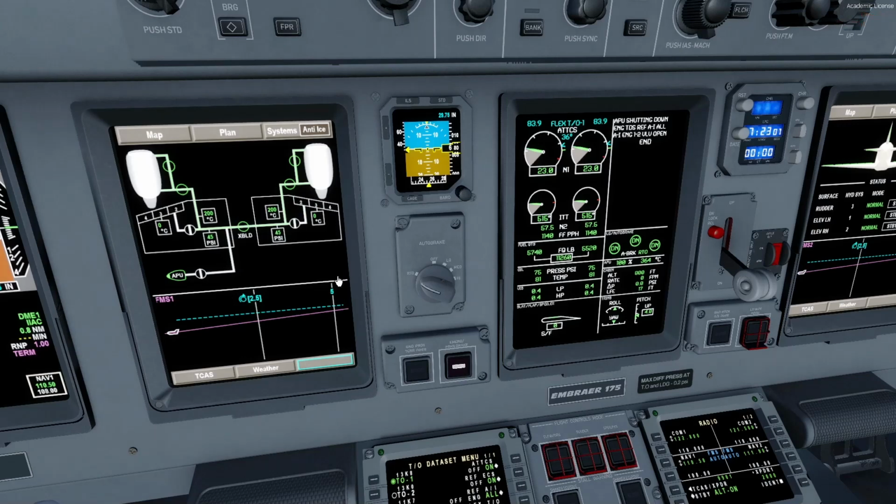Okay. Now, why is the wing anti-ice not activated yet? I told the airplane, hey, I want the entire anti-ice system to work. Why is it not operating? So the reason is it would not activate while taxiing, and it will automatically activate once we are accelerating past 40 knots during the takeoff roll. Then we would also see the wing anti-ice valve open. So obviously the APU would not be part of this equation at all, because as we said, I think that's the third time, the APU cannot be used for wing anti-ice purposes.